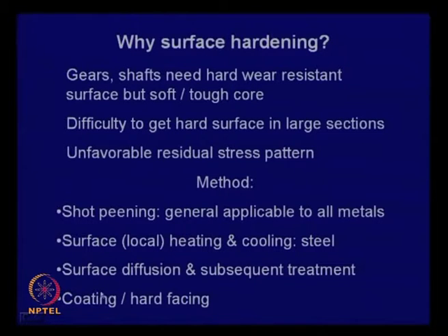And apart from this, there are lots of other coating processes where you can give hard coatings, and usually you may have to give multi-layer coatings to maintain compatibility with the base material. You may have to give several layers of coating, a bond coat, and ultimately a hard, wear resistant coating, or for some materials you want a thermal barrier coating.